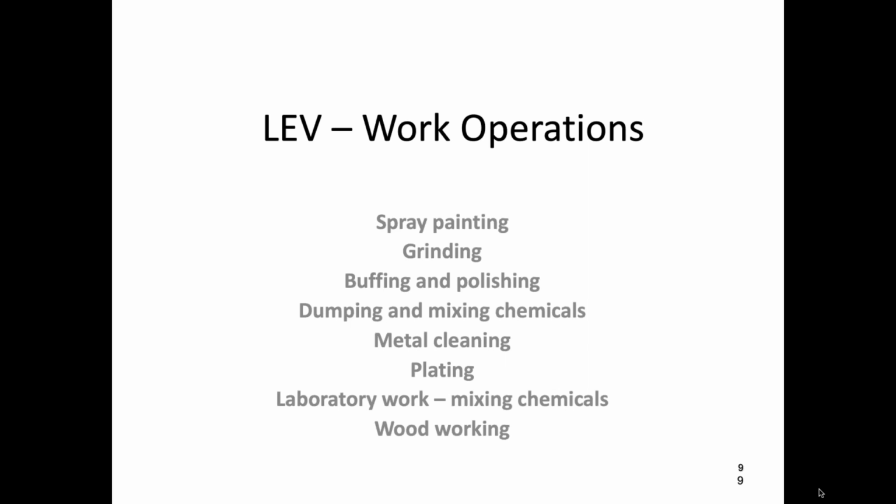So you have spray painting operations, grinding operations. In other words, a guy that's grinding mortar between the bricks on buildings. You don't want him being exposed to all that silica and dust and caustic dust from the cement or the mortar between them. So those grinding devices now have hoods on the machines themselves, on the devices that they use to grind, brushing and polishing operations, metal cleaning, plating.